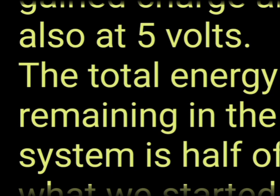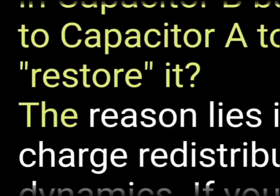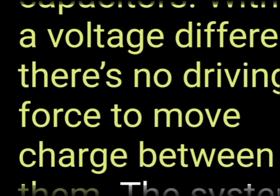But why can't we send the remaining energy in capacitor B back to capacitor A to restore it? The reason lies in charge redistribution dynamics. If you connect capacitor B at 5 volts back to capacitor A, also at 5 volts, there is no voltage difference between the two capacitors. Without a voltage difference, there's no driving force to move charge between them. The system is in equilibrium, and no further energy transfer can occur.